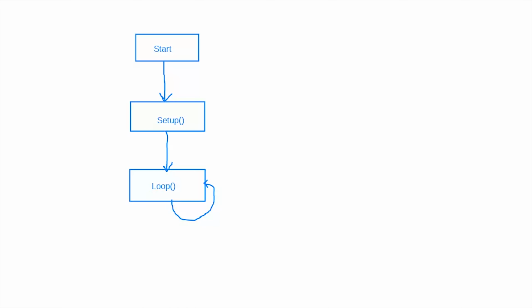Outside the setup, you can have your global variables and variable declarations. The setup runs only once, whilst your loop runs forever, so the loop will keep running as many times as possible. Just bear that in mind when you run your code.